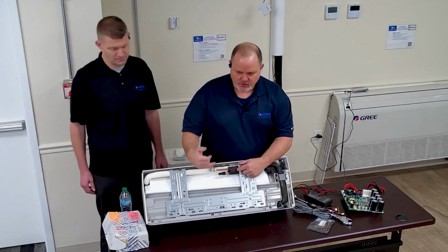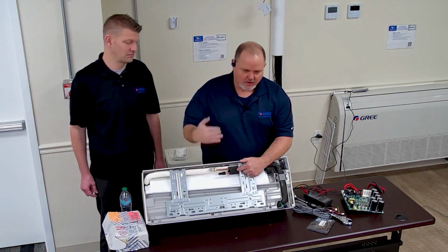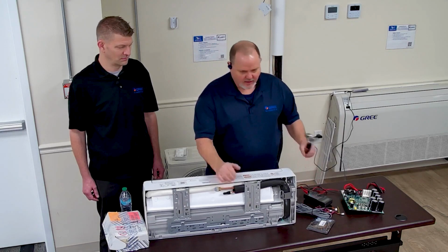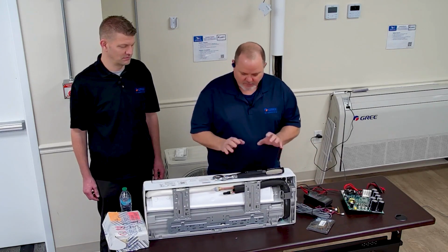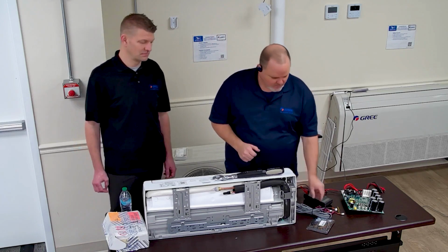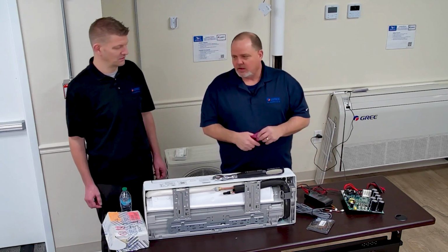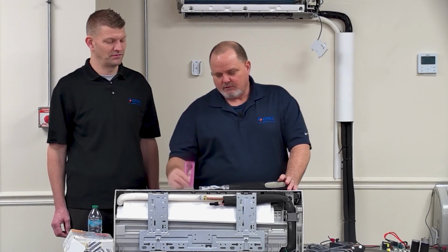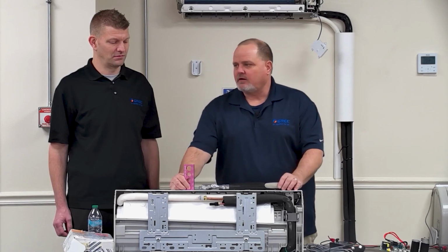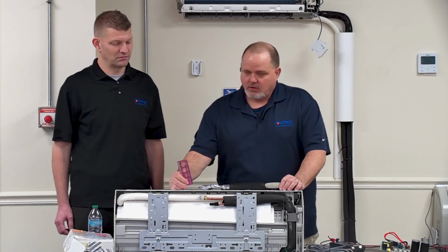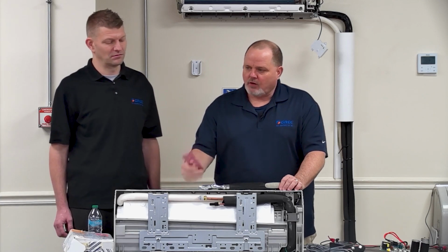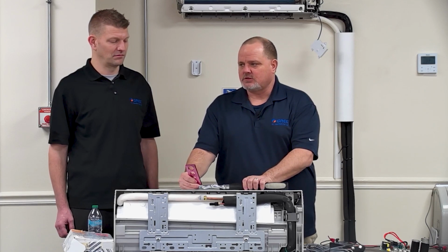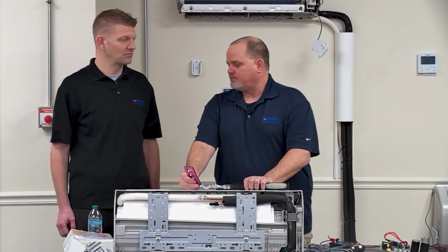The advantage that you guys have to doing flares today compared to doing flares years ago is we now have proper torque wrenches, we have torque specifications to torque those nuts to, and you even have good quality flaring tools. You even have power flaring tools, and they even give you flare gauges to make sure that when you flared that flare, it's proper. So as long as you're using a flare gauge, cutting that pipe, reaming the pipe, flaring it properly, and torquing it to specification, you shouldn't be having issues with flares.